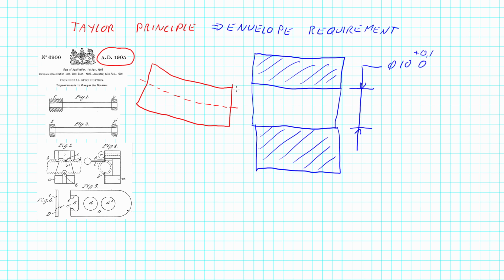And maybe the tolerance for our cylinder here, our shaft that has to fit into it, is again a diameter of 10, and maybe that's then plus 0 and minus 0.1. So in principle, they could both be 10 exactly, which means that they should fit together.